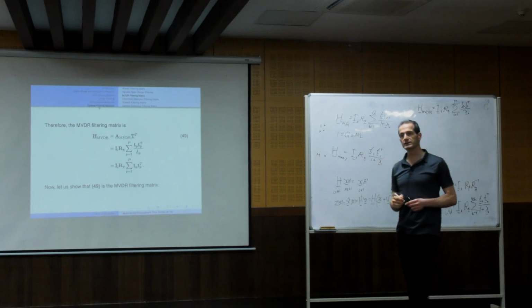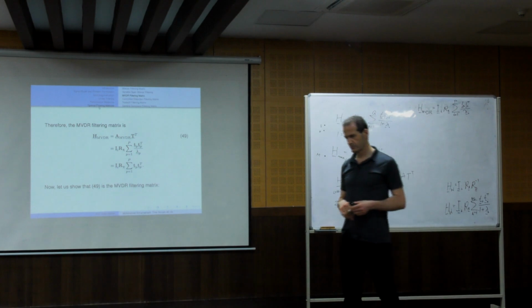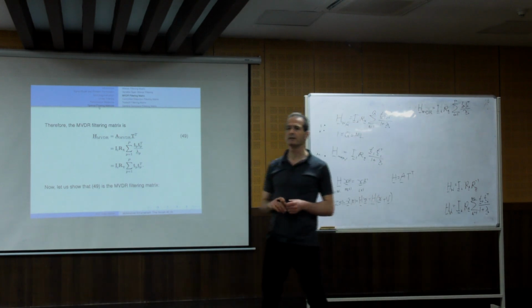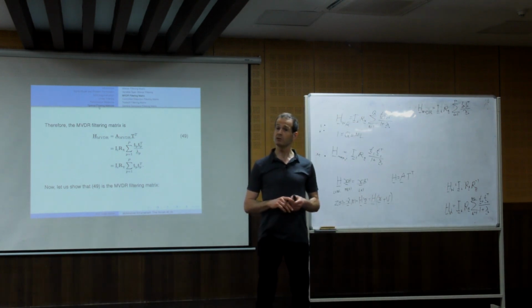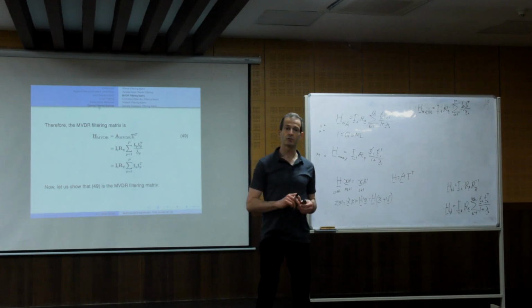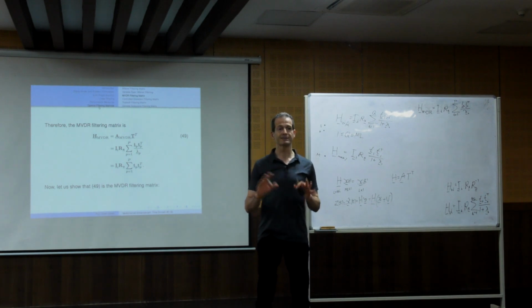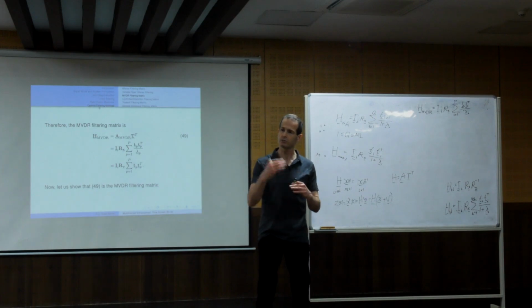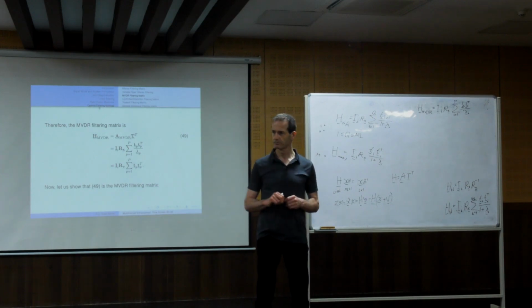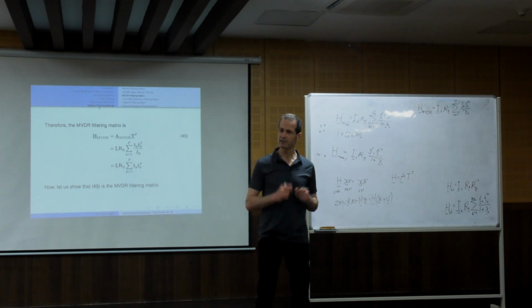Now we have an expression for the MVDR. Now suppose that we want to enable some distortion in order to reduce more noise. The MVDR reduces the maximum of noise without any distortion. Now suppose that I want to reduce additional noise, and to pay with some distortion.